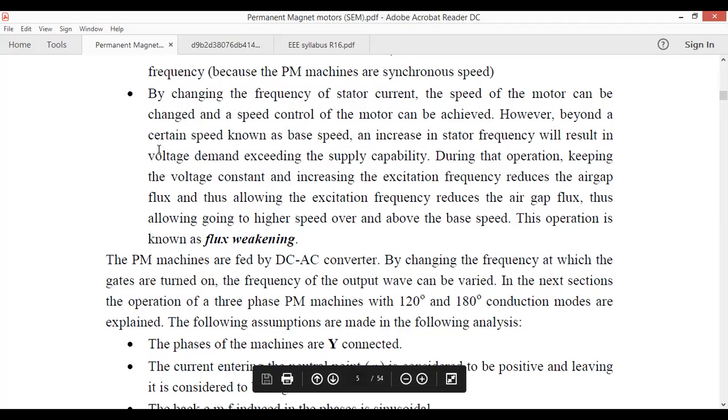Here, what these terms mean is that from the alternating current supply voltage side of the motor, given to the stator winding, it is possible to control the speed, above base speed or below base speed values. So we allow a change in the frequency value, and we even change the V by F ratio also.